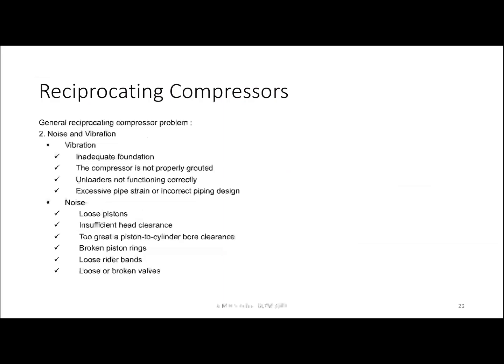Now another problem in a compressor is high noise. It can be caused by a loose piston. A loose piston can bring a lot of problems, such as insufficient head clearance, or too great a piston to cylinder bore clearance. It can also be caused by a broken piston ring, loose rider bands, or loose or broken valves. These are several problems for noise.